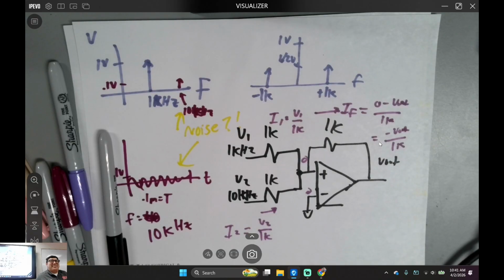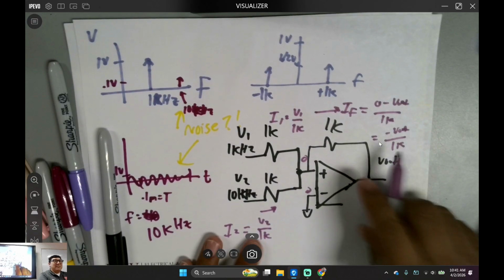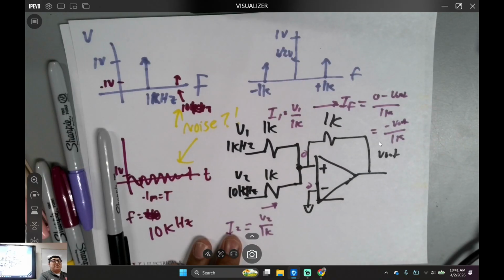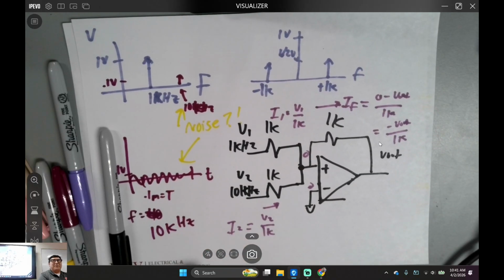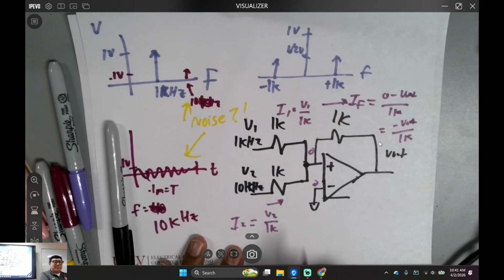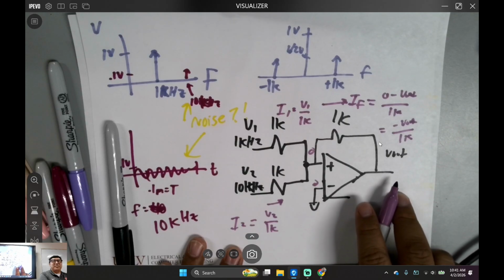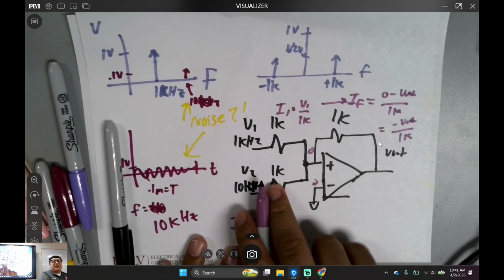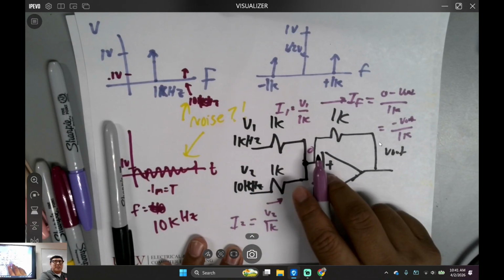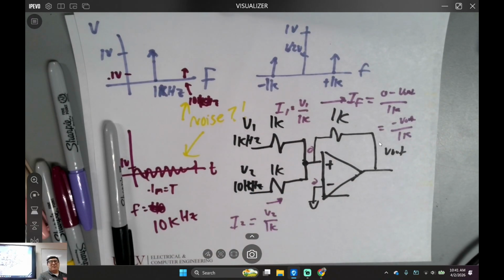This is not that hard. And then we can find what V out is with respect to V1 and V2. Everyone knows how to do a mixing circuit. Series mixing, shunt sampling. We're sampling this output, and it's a voltage. The input is a current, right? The output is a voltage.